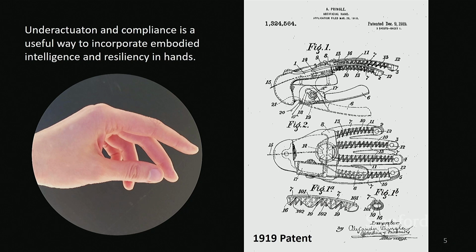And then when we go one abstraction layer higher, we've got 4 fingers, and they are all being actuated by a single tendon. And it shares loads between them with this pulley device. So if one finger moves back, the others will move forward. And this is, I think, a pretty clever mechanism. So people have been pretty good at thinking about this for a long time.